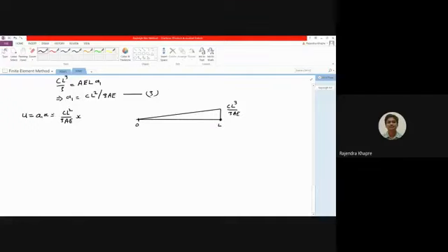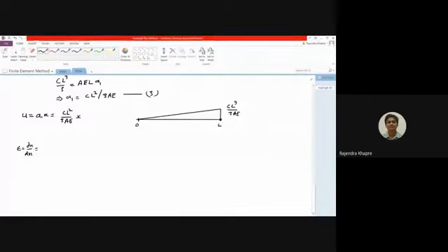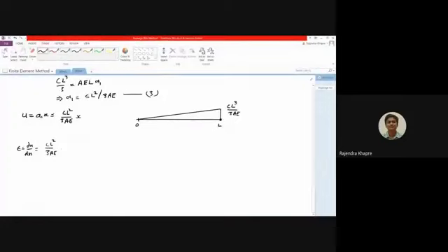Now let us see the strain component. If you calculate the strain, strain is nothing but du by dx. Okay, so if you take the derivative of this particular expression, this will be something like C L to the power 2 divided by 3 times A into E. There is no X component over here. So this X component will be completely gone. So this is nothing but A1 over here.